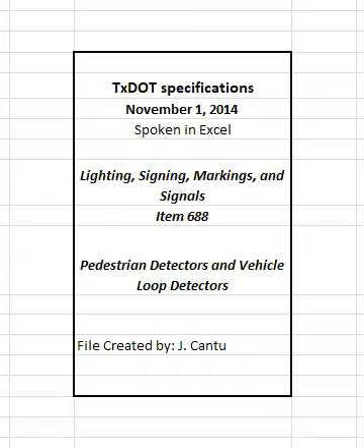Splice the loop lead-in cable and loop detector wires only in the ground box near the loop it is serving. Use non-corrosive solder for splices and ensure the splice is watertight. Ground the drain wire of the loop lead-in cable to earth ground only at the controller or detector cabinet. Ensure the resistance from the drain wire to the ground rod is less than 1 ohm.